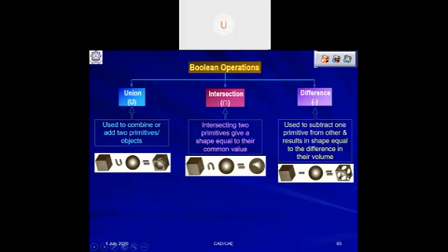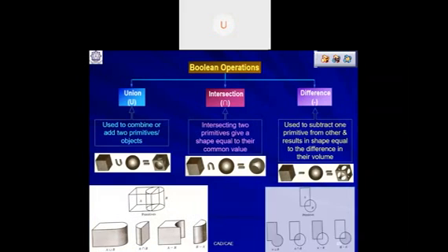So this last one is very difficult by using the feature approach, but using your primitive approach, you can easily create this one. With two very simple primitives, you do the Boolean operation difference, and you can easily create this one. So that is why sometimes the primitive and Boolean operation based approach is also used. So it is a combination of both the feature based approach as well as the primitive based approach. So most CAD software nowadays combines these two. You have to take advantage of both methods or both approaches. So this is another example of this one.